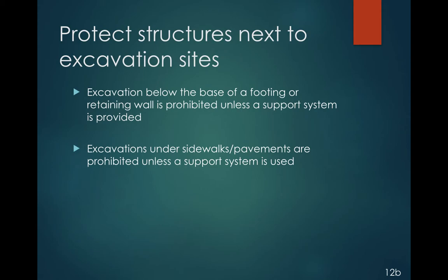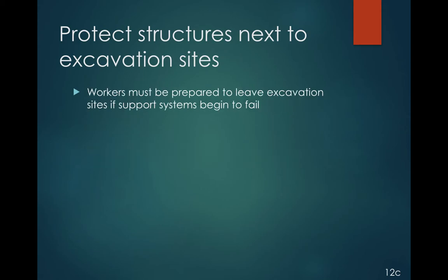Excavation below the base of a footing or retaining wall is prohibited unless a support system is provided. Excavations under sidewalks and pavements are prohibited unless a support system is used. Workers must be prepared to leave excavation sites if support systems begin to fail.